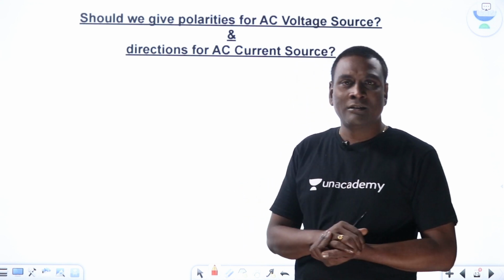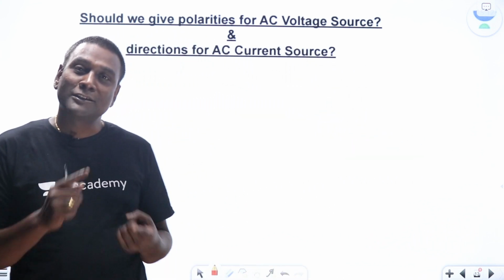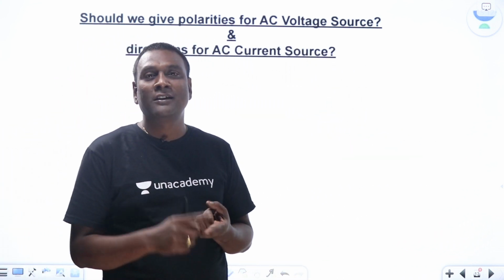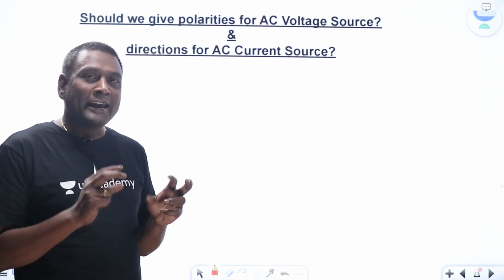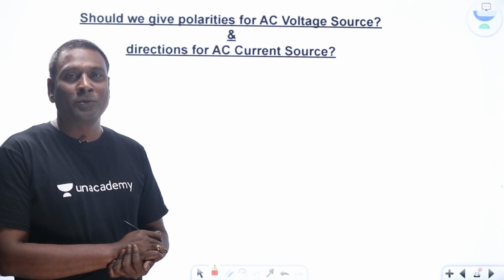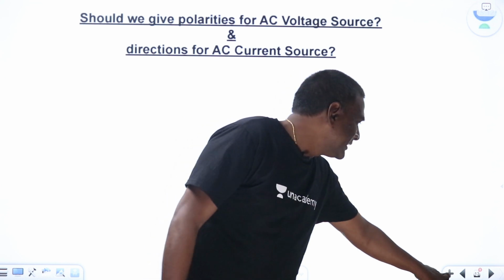But as per our previous discussion, direction should compulsorily be specified for current and polarity should be given for voltage. Otherwise, the direction of energy transfer will become unknown. If you don't know the direction of energy transfer, it is going to be foolish, because we can discuss the analysis of any electrical system later. But first of all, we should know whether to supply energy or absorb energy, in the electrical form.